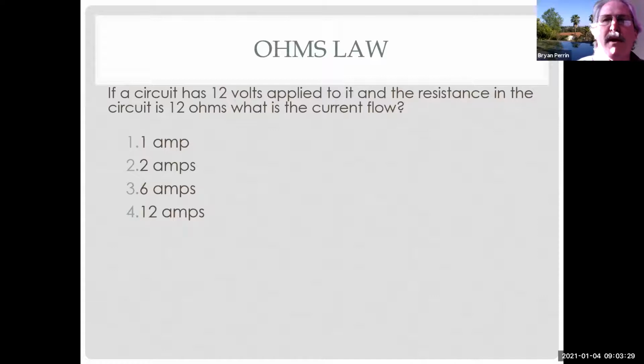So I've started at my battery positive. I've gone through my wire, through what we call a load. Now, a load, as we'll see, can be a motor, it can be a light bulb, it can be any number of things. And then completed my path all the way back to ground. So a complete circuit has current flowing through it. If there's no current flowing through it, then I don't have a complete circuit, and Ohm's law is not going to apply.